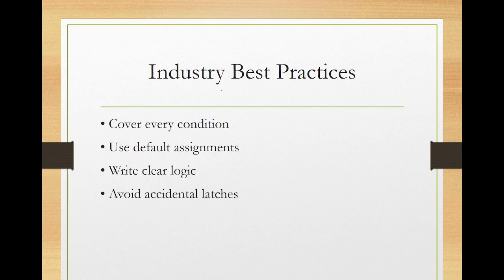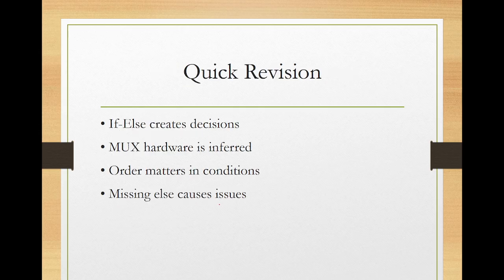Professional RTL engineers follow simple rules. Always cover all conditions. Always think about missing paths. Always provide default assignments. Always avoid unintended latches. Good RTL isn't about writing code. It's about controlling hardware creation.